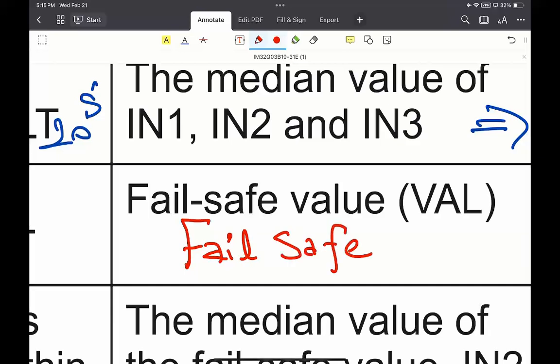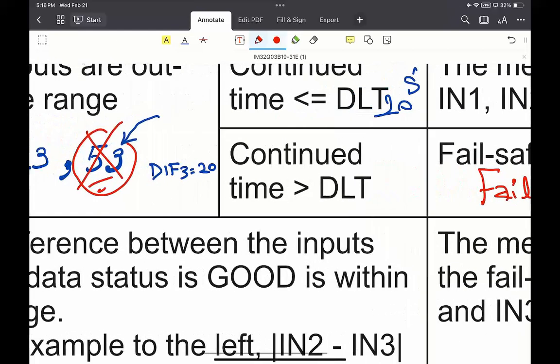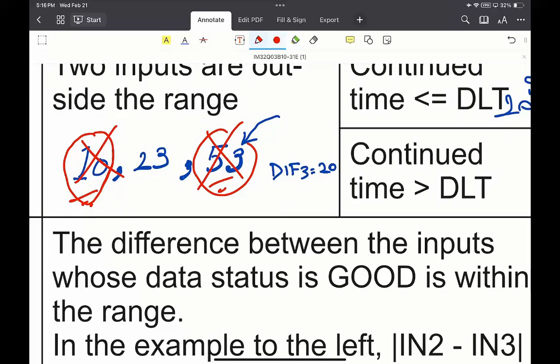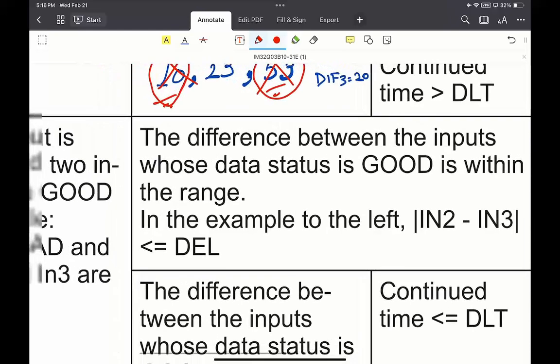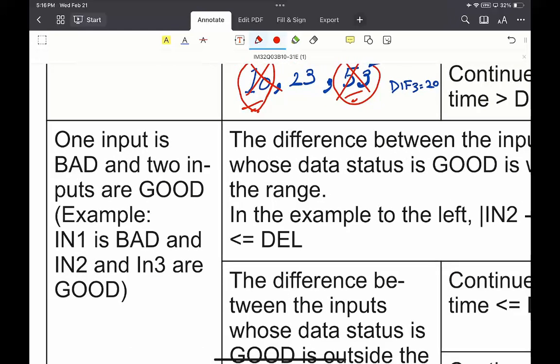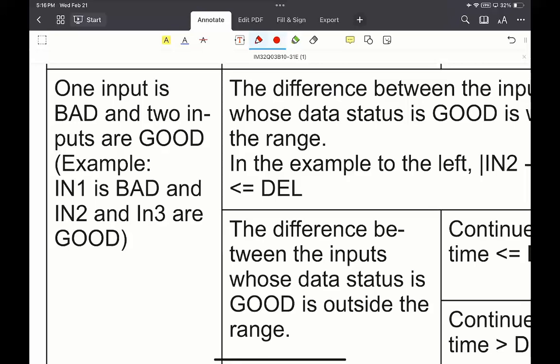And in most of the cases, failsafe for temperature, normally we consider the high limit, and for level, I guess we can use most high and low. But if I had the chance to select the maximum 100% for level, I will select. And this will be a shutdown because we ignored two transmitters with the deviation, and that's not good for operating a fail-safe loop. We use two out of three in critical processes in a boiler or anywhere when there is a voting system.